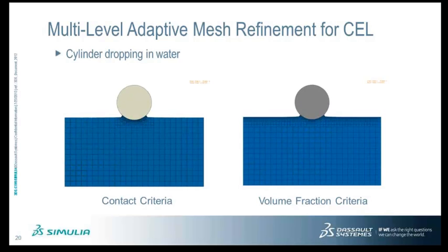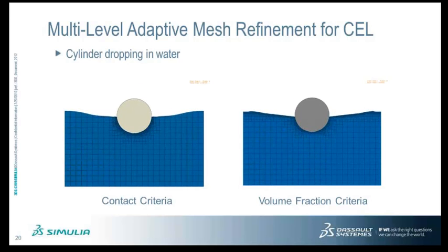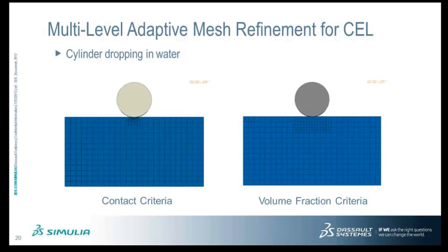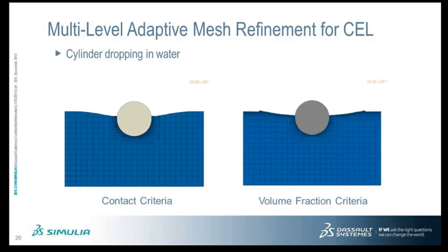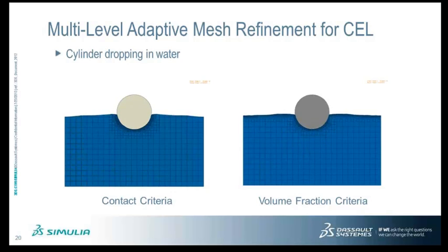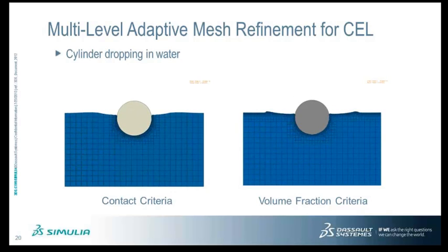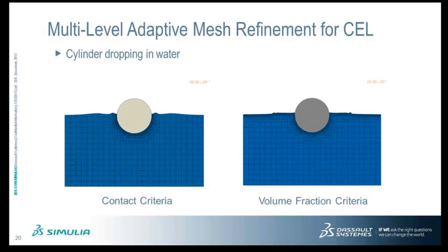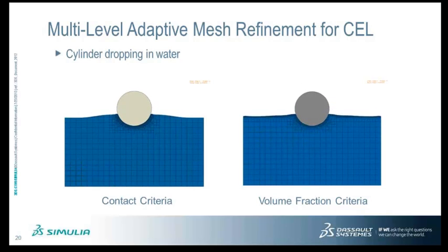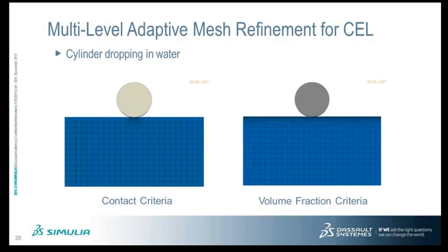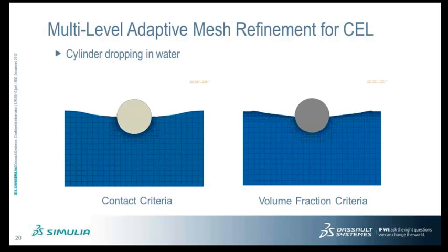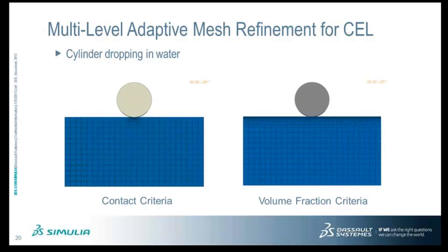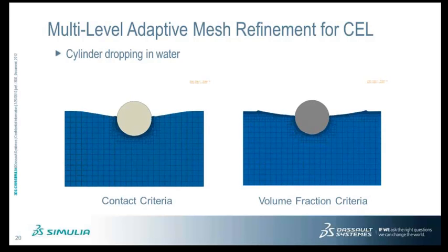This enhancement is designed because these Eulerian meshes for the CEL analysis sometimes tend to have fairly large domains, and these are structured volumes. But a lot of times there are some areas where you need a refined mesh to capture the behavior, while away from these areas you can get away with a coarser mesh. And just from a performance standpoint, this can be quite a benefit.